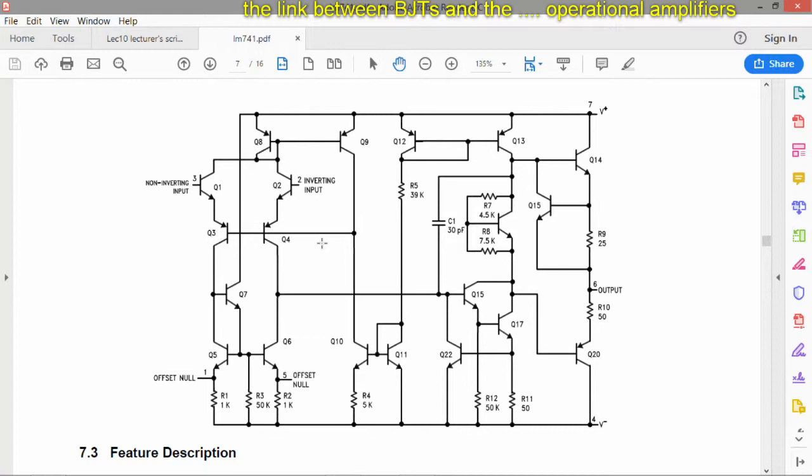This is a real leap, but starting from where the non-inverting output is a Darlington pair, and there seems to be another one on the inverting output. So do they make a differential? So I think you are right. So we can see here this part, where effectively the non-inverting input and the inverting input of the overall amplifier is that circuit.